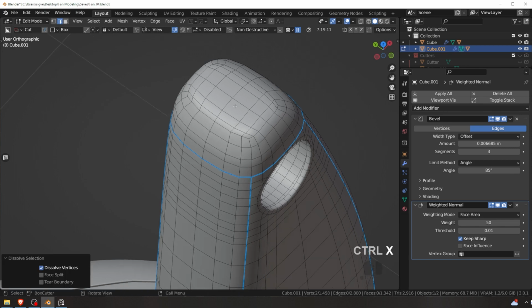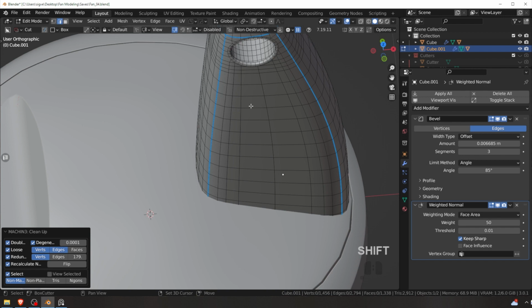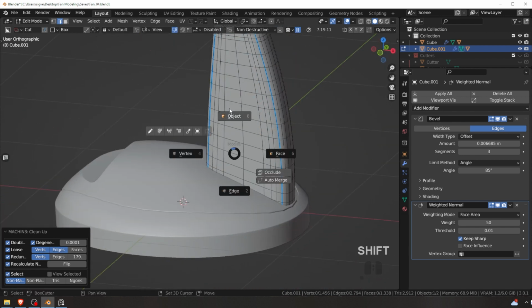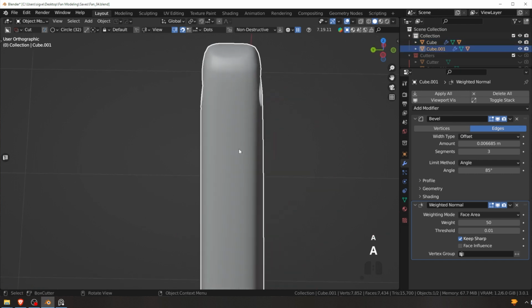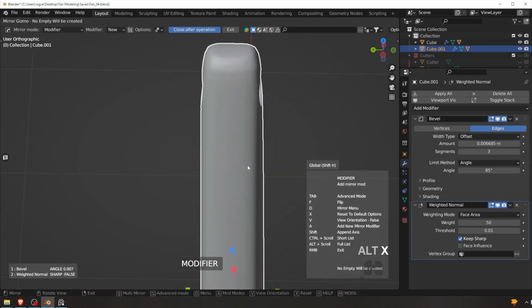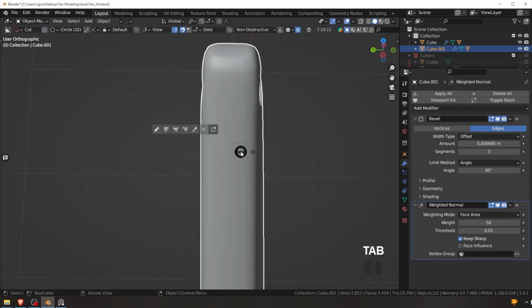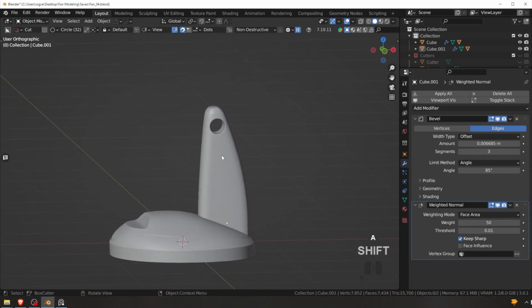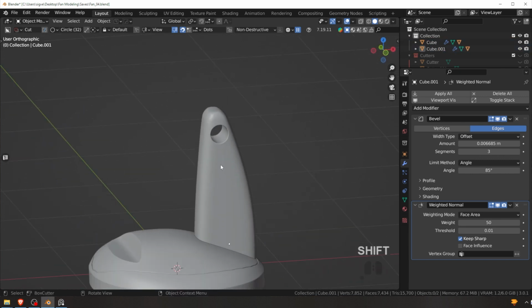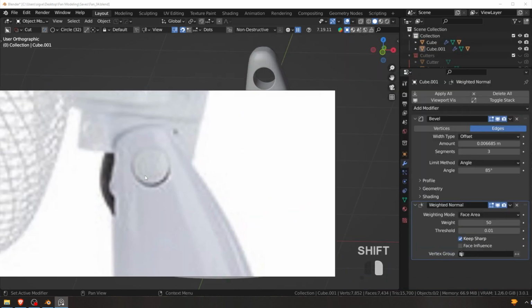And in the center it might create some stuff, so let's just select everything, press 3 to clean up stuff in there, and boom, so we symmetrize it to the other side. If you don't have Mesh Machine, you can just select the whole mesh, click Alt X, and then select this axis. That's mirroring with HardOps. Yeah, so boom. Now this part is actually done. There we go. That part is completed.